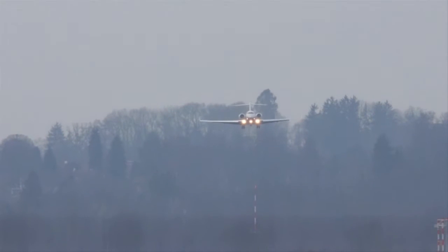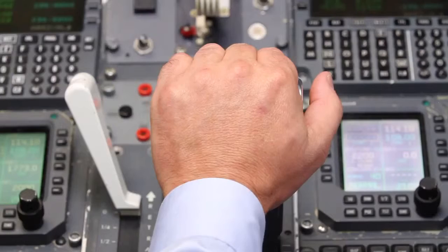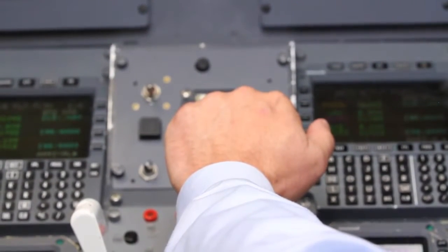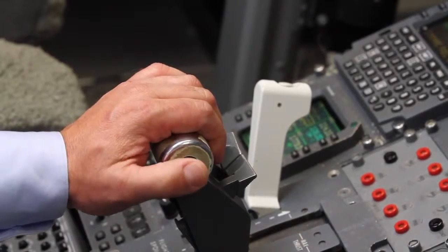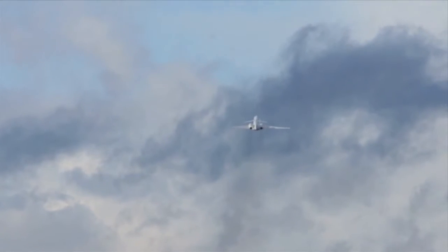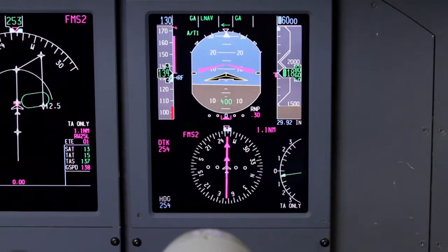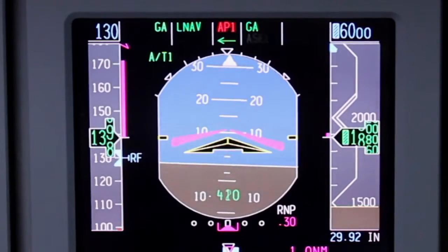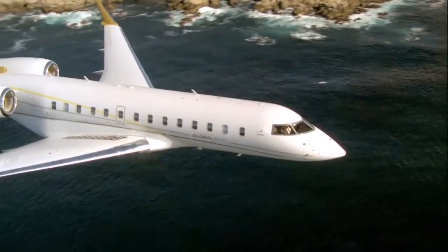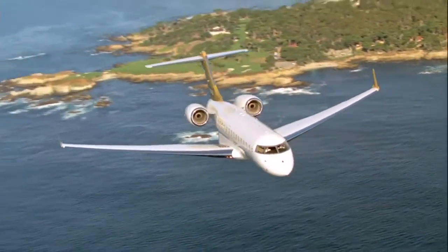As the aircraft reaches the LPV decision altitude, the pilot must either continue to land or initiate a missed approach. When a missed approach is initiated and the TOGA button is pushed, navigation guidance automatically transitions from GPS back to FMS. For aircraft equipped with FMS version 6.1 or later, LNAV remains as the active lateral mode during a go-around. For aircraft equipped with earlier versions of the FMS software, the lateral mode changes to roll during a go-around.